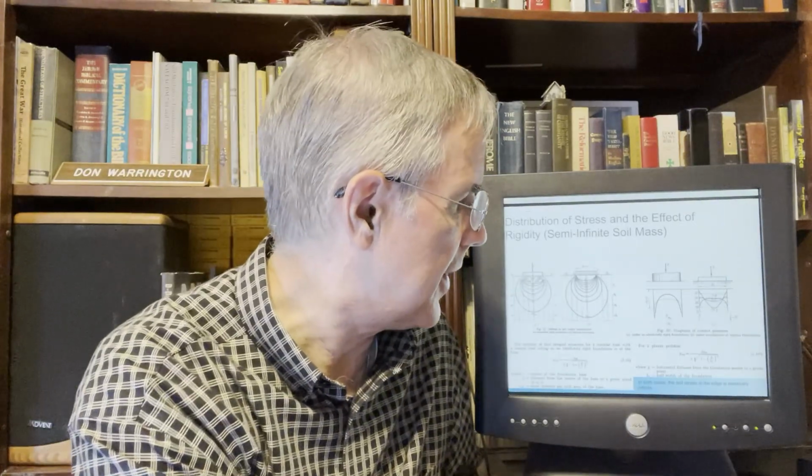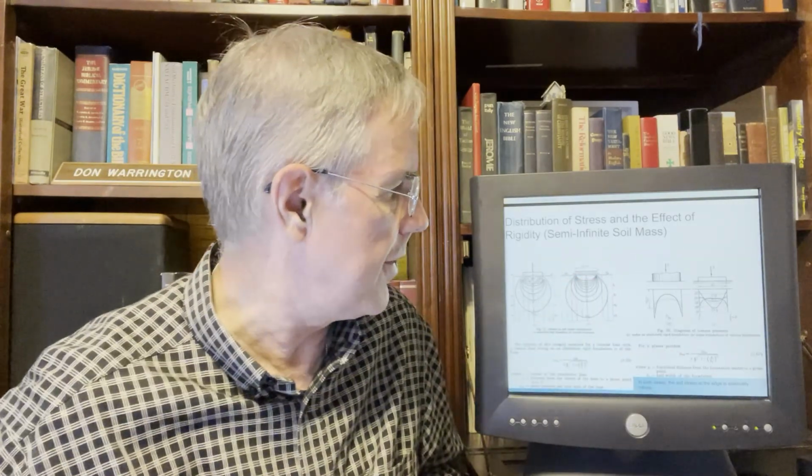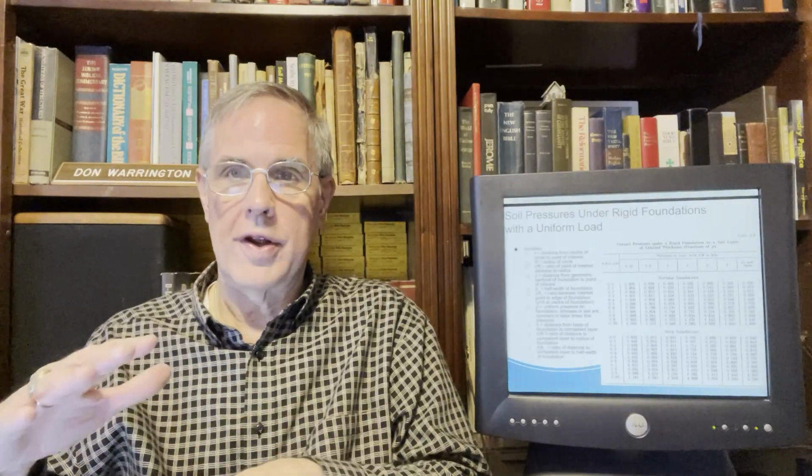And actually, if that is shown, it's kind of weird the way he's got it, but right here you see that. 2B1, they actually talk about the half width is B from here to here. Sometimes the notation doesn't quite hold up, which is why I have to keep redefining it with every table. P is uniform. H is the distance, consistently, from the base of the foundation to where the incompressible layer hits.